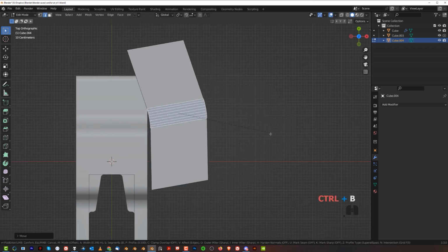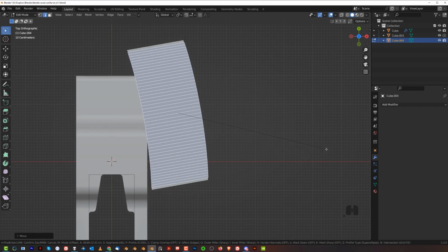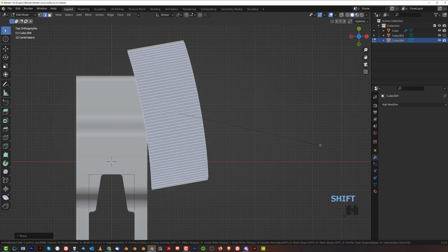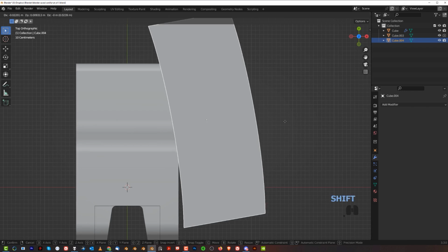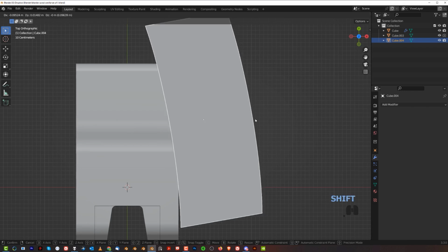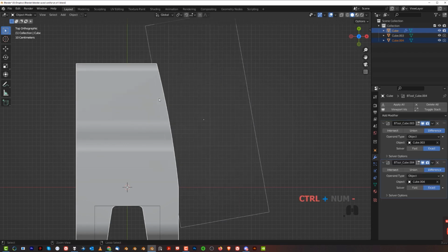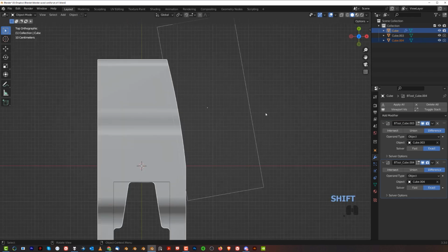And we're going to create a really nice round chamfer. Bevel, add a lot of segments, maybe, I don't know, 46 will do, maybe even more. Let's go with 50. So it's going to be nice and smooth, and we want to cut this shape here like this, okay? So bringing it close here, and shift click this one, and Control minus, and you're going to get this nice sort of rounding effect.